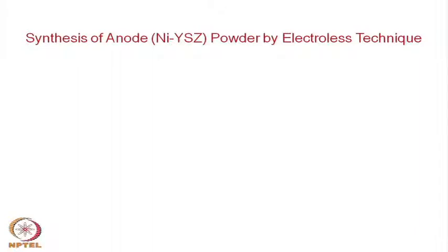like solid state sintering, which is one of the oldest ceramic processing techniques one can use because they are basically mixed oxides. So, two of the oxides of concern can be put together or mixed together and put at a high temperature. So, there will be a high temperature chemical reaction and the mixed oxide will be formed or a solid solution will form just like YSZ.